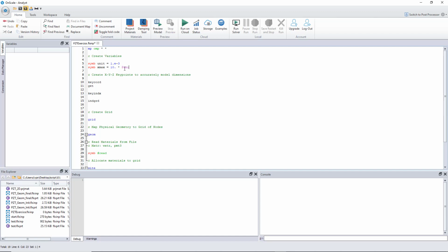So when you call a variable, you put this $ sign. Don't forget to put a space in between each instruction and the multiply in the middle. So every time I write a variable, which will be in millimeter here, because everything is in millimeter, but my model should be defined in SI unit, in meter unit, so that's why I need to multiply all this by this. Okay, anyway, I have the X max of my grid.